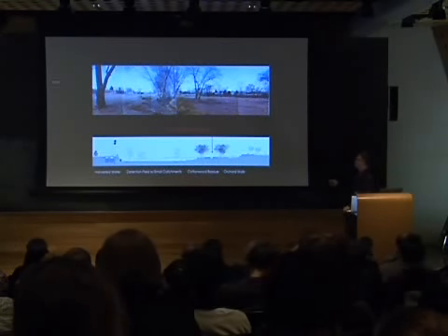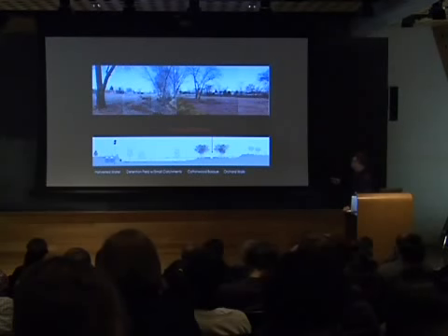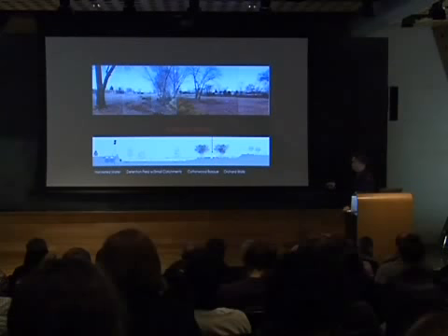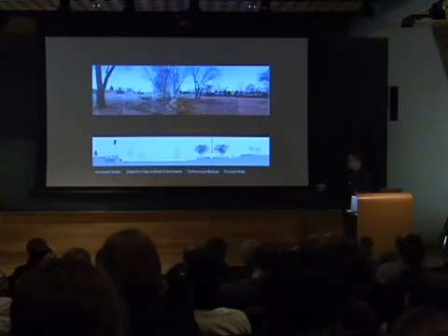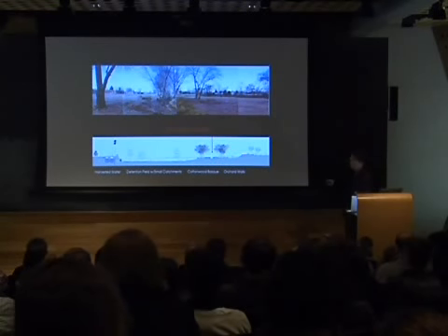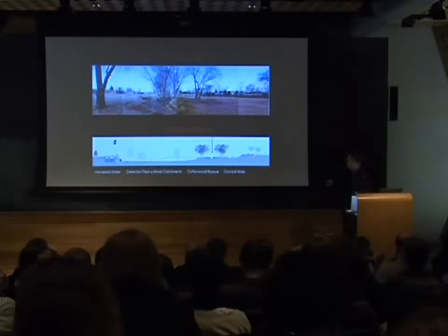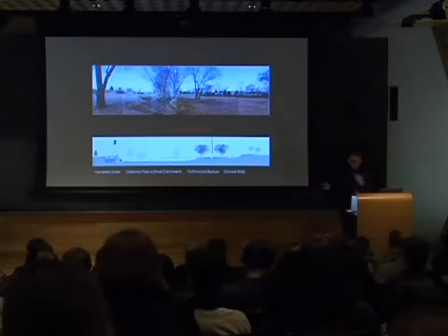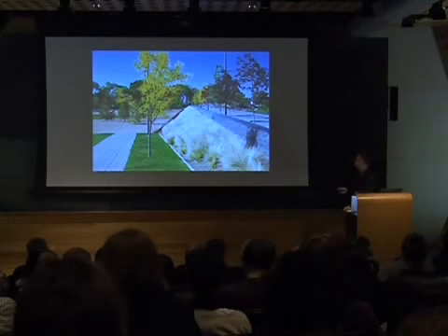And this is what the site looked like when we started. And you can see this was the original terrain, largely flat. This is the Acequia Madre. And we quite dramatically changed the topography of the site to create a very large catchment area. And the large catchment area then has small catchment areas. And there are small catchments woven throughout the site to hold the water. And we also used gabion walls to capture water and to help infiltrate it into the soils.